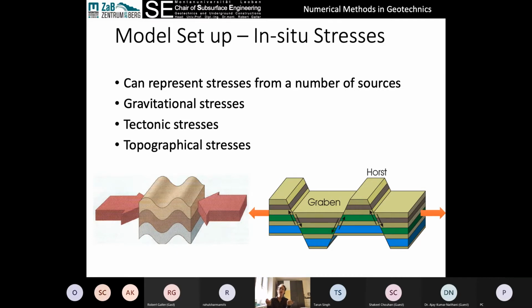In that case, we have very low horizontal stresses in the pulling direction. So getting a feel for those stresses is important, and there are lots of courses in site investigation, rock mechanics and soil mechanics for estimating them. But it's important not to just use the depth and overburden for sigma v when you're in a deep tunnel.